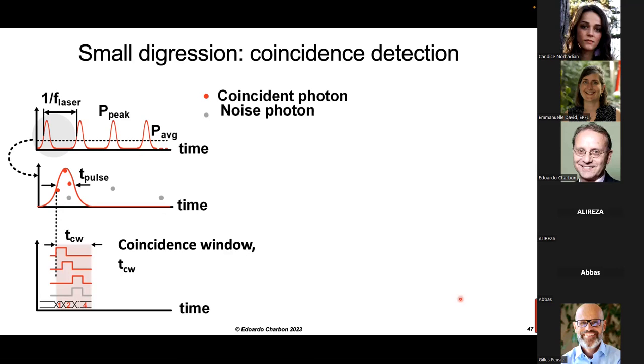So for each and every one of the measurements, you can measure the time of flight. By doing so, you can simultaneously have information about the depth of the object that you're looking at, and at the same time recognize who has generated the pulse. So every pulse could be coded differently and detected independently.